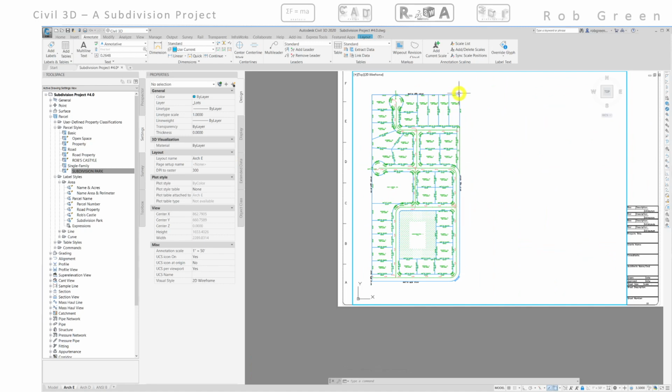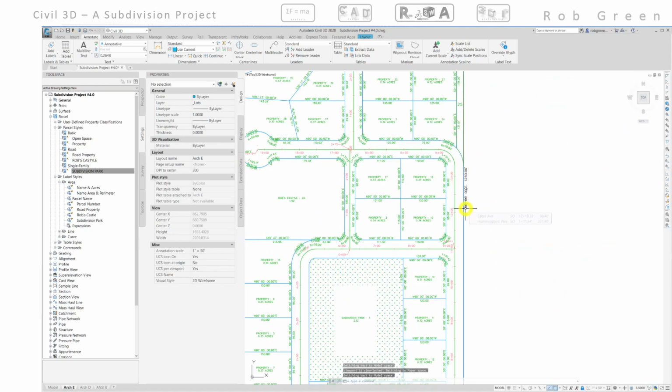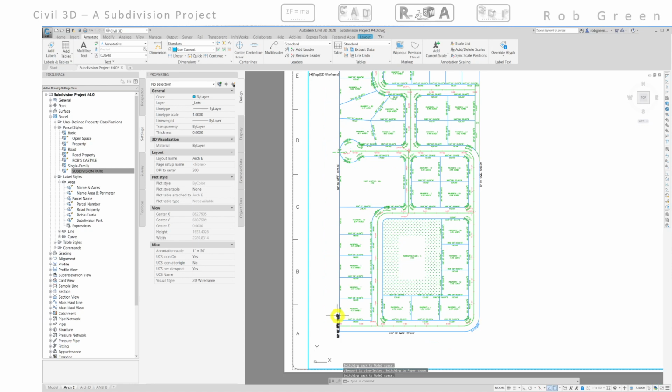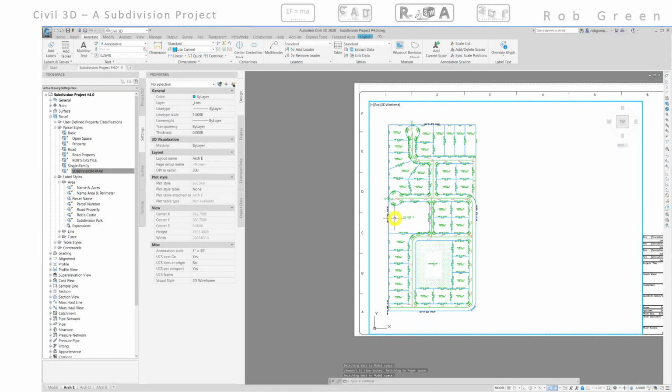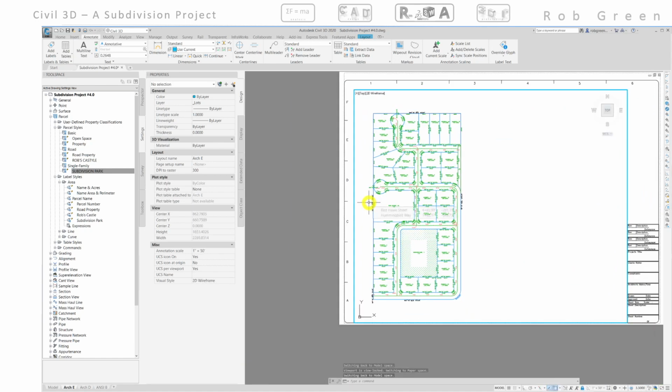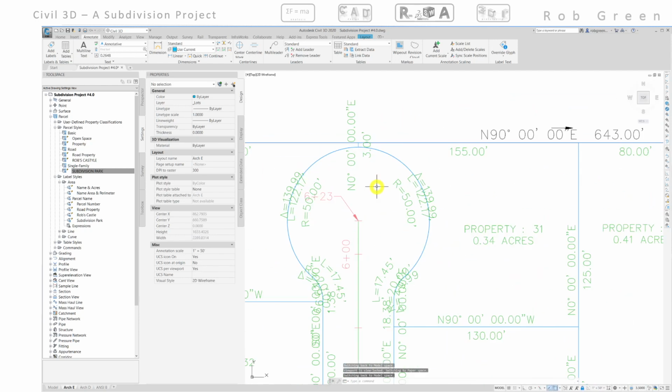So if my label goes from north to south, or my selection picks, then the label is going to use south as a prime axis. If I'm labeling from a south pick to a north pick, my label will give north as the prime axis. So important to be aware of that. And again, we want to go around in a consistent direction throughout our project.